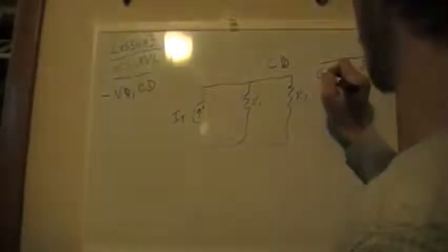Now, if you guys remember what I said before, in order for this current to split, elements have to be in parallel with each other. So what we had before was a series circuit where the resistors were hooked up to each other like this and fed back into a source. Well, that is a series combination. This is a parallel combination. And in order for current division to work, you have to have a circuit set up that looks kind of like this. Otherwise, if you had the other one, current is the same, so it won't split at all.